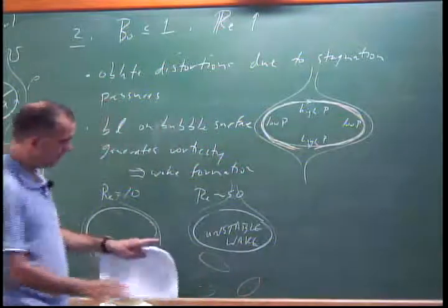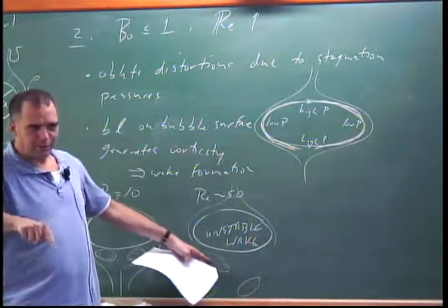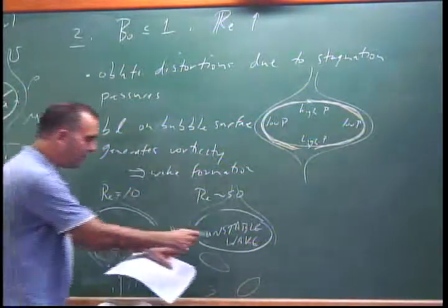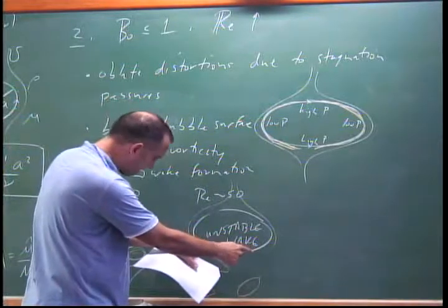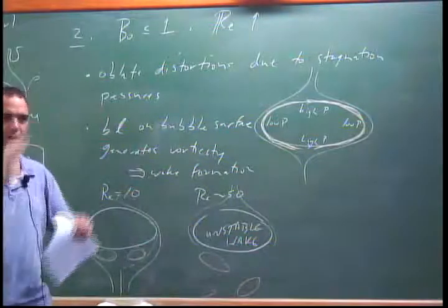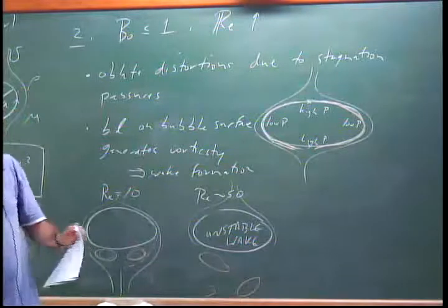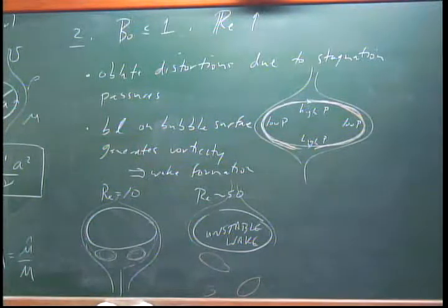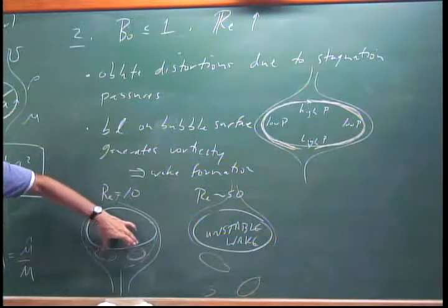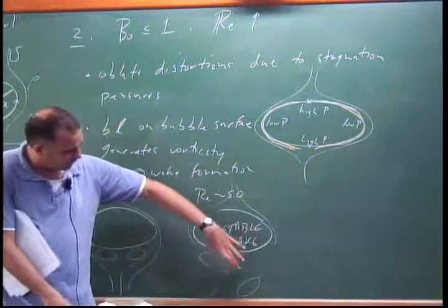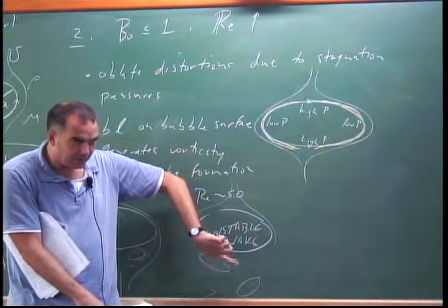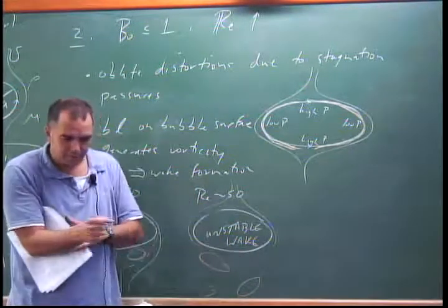And so basically these are, again, vortices, so they're the sites of high speed and low pressure. As they're released, you break the symmetry in the pressure distribution on the bubble, so it actually goes like this. So the bubble actually wobbles as it goes in response to these vortices being shed off the back. Again, if you have flow past a cylinder, you have the same sort of thing. Imagine this was a rigid object. You just have these things sitting there, would be fine. And then at a critical Reynolds number, this wake goes unstable, and you start releasing vortices, and because of their influence on the force on the object, it will actually start moving like this.